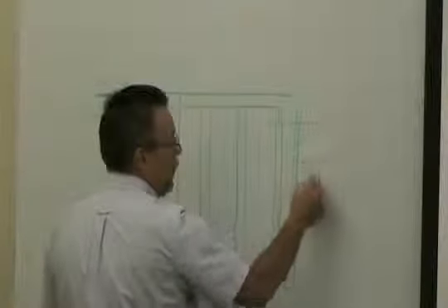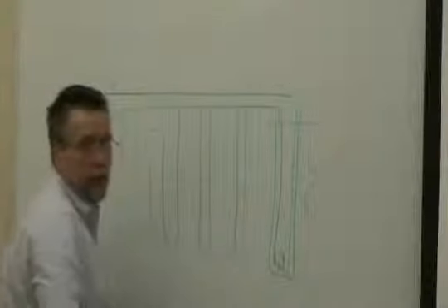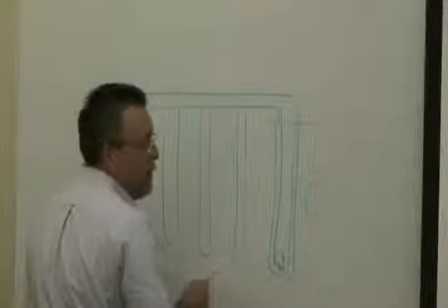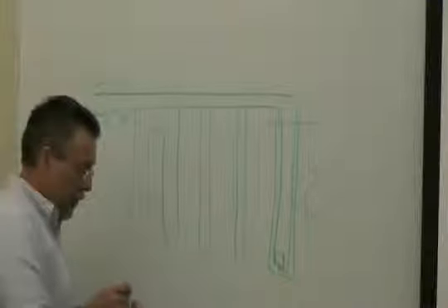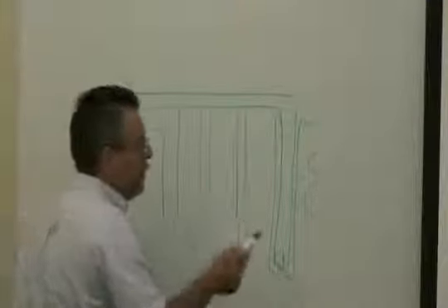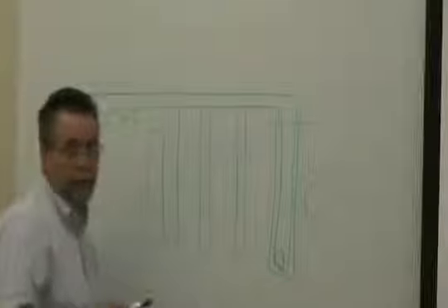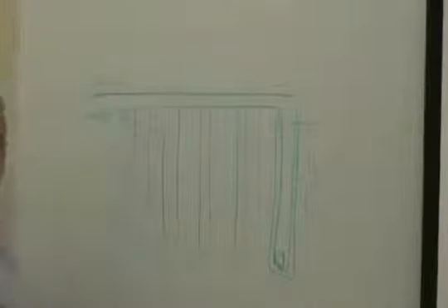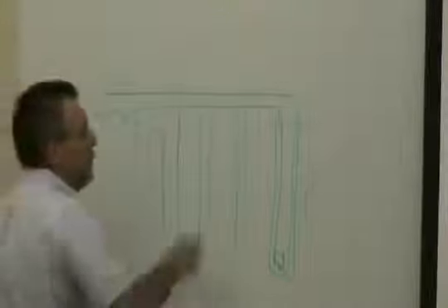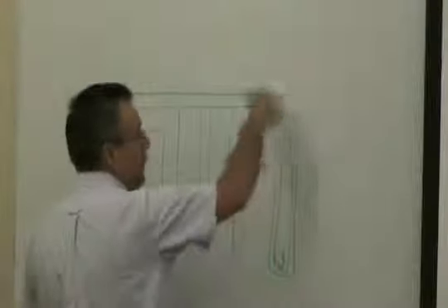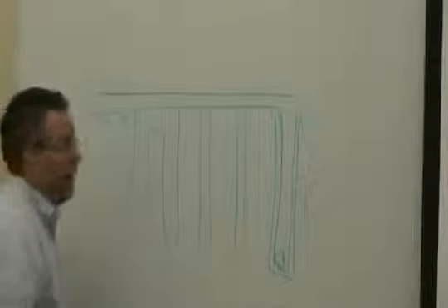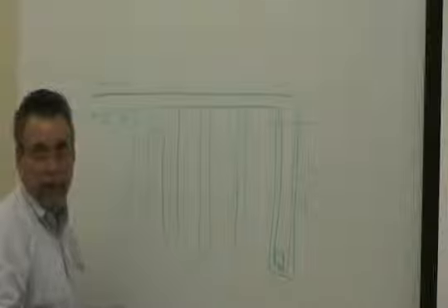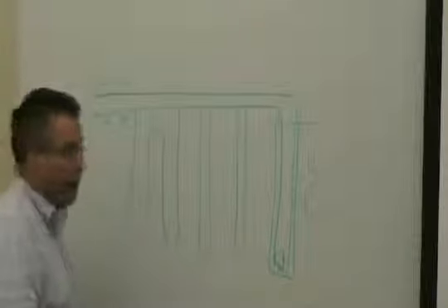Generally it's a 4 to 6-inch well that's being drilled 250 to 500 foot deep. Do they always get water, or do they just open it up? No, what you normally do, if you're going to do a geothermal application, is come out and drill 1 or 2 test wells, and they test the ground. They actually heat the water up, put it in the ground, and bring it back up to have a heat source. They're testing the conductivity of the ground to see what kind of heat rejection or heat absorption they can get out of the ground.